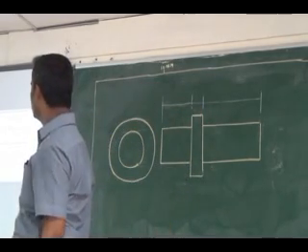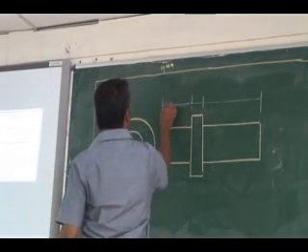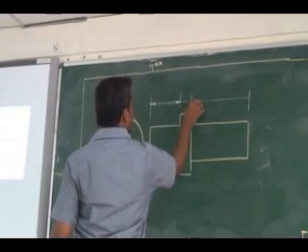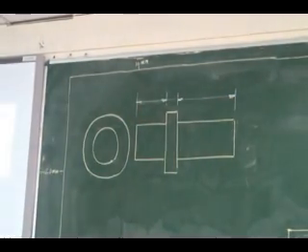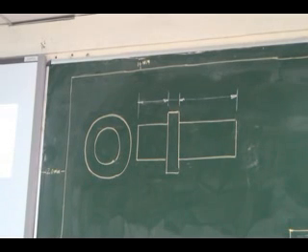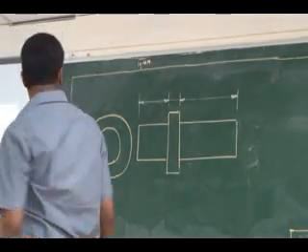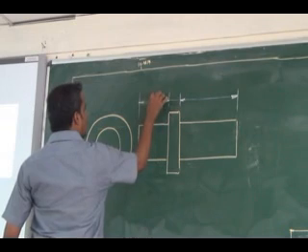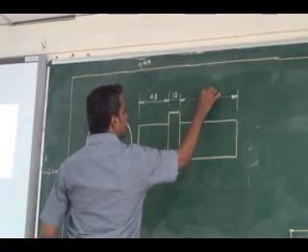That is also drawn in a 2H pencil. Then the dimension as such with arrowheads. These lines, dimension line, extension line, and we will come to the hatching lines later. These are all drawn using a 2H pencil, that is called a continuous thin line. So you will have some value for this. This is 40, this is 10, this is 70.